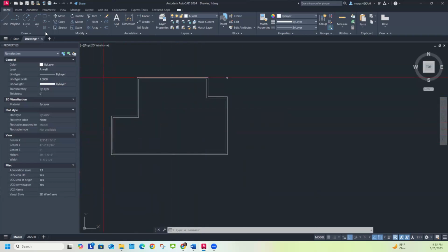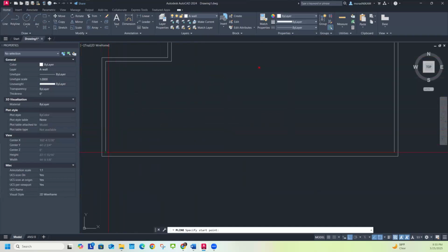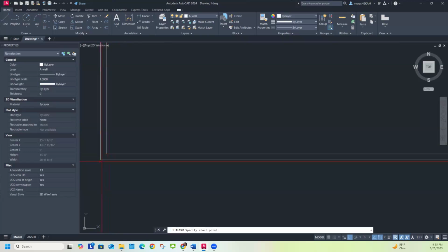Okay, so I'm going to go ahead and add my interior walls according to the drawing that I have for the assignment. So I'm going to go over, let's see. It's actually going to be drawn from the exterior one, 8 feet 3 inches. So I could take this, I'm going to hover over it, start going. Let me escape that. I'll start from here, start going in this direction, 8 feet dash 3 inches.